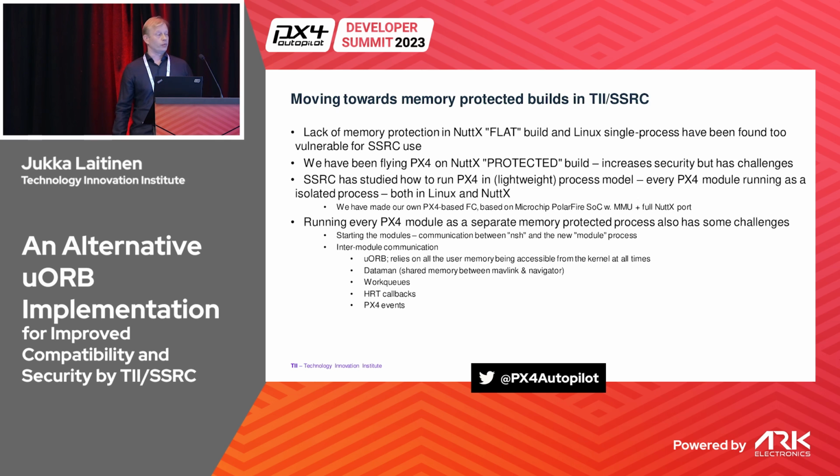And we have our own flight controller hardware based on a microcontroller that has an MMU, so it's an application-grade microcontroller. We are using Microchip's PolarFire SoC. It's a quad-core RISC-V microcontroller, and we have built several variants of the flight controller out of that.